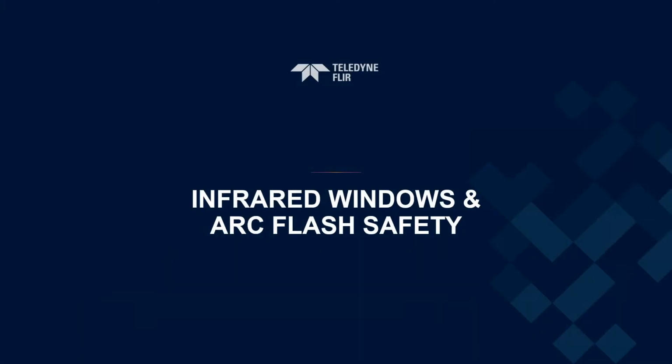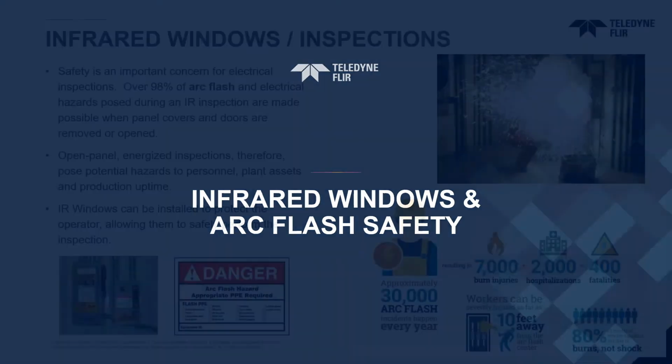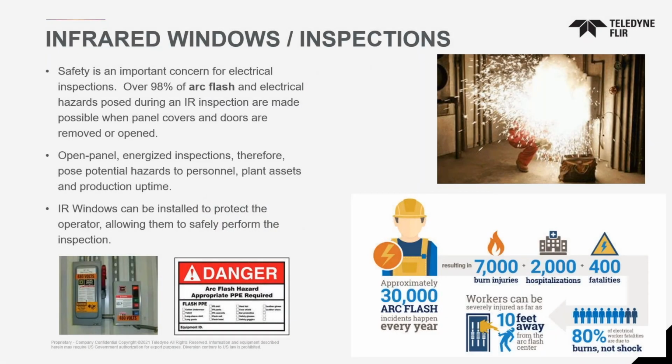Now, part of infrared thermal imaging, which is very important, is infrared windows. It's a hand-in-hand technology, especially if you have a lot of cabinets, electrical installations, and electrical rooms. Why? Because of arc flash safety. Arc flash is a major problem in the electrical world. For people who are unattended or not prepared for it, people have died and been injured. A lot of things have happened because of arc flash for people who are not familiar with it. So to reduce the risk, we always recommend putting in an IR window.